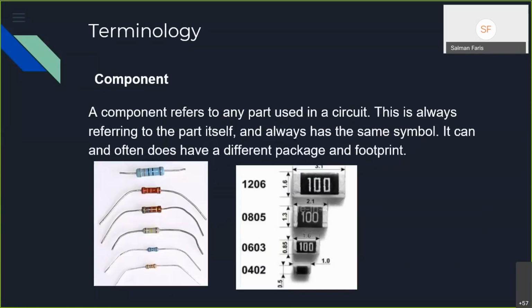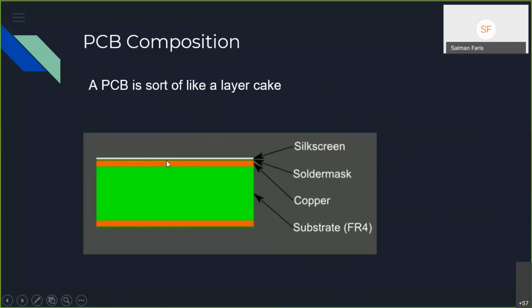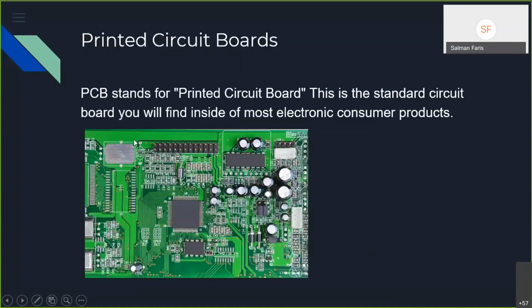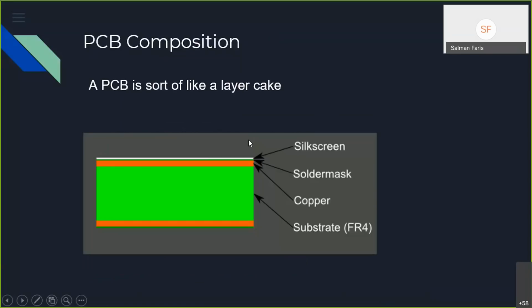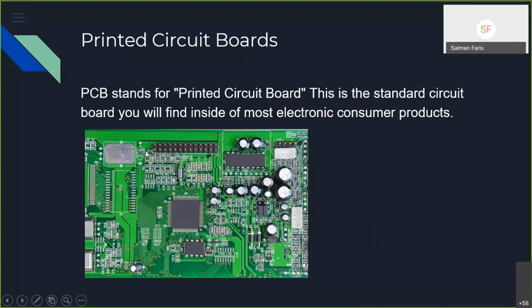Okay. Next we can check our PCB. You can see this is the solder mask, the green one. You can see these icons are the Silkscreen. The white lines are Silkscreen, and you can also see some through-hole components. These are through-hole components, and these are surface mounted components. You can see through-hole capacitors, and you can see SMD components here, like this one, and some of these components are not soldered yet.